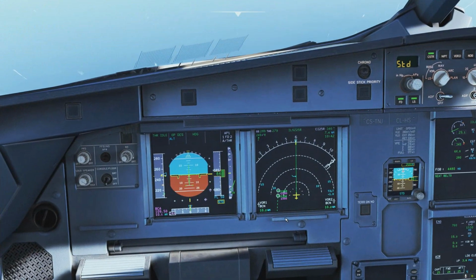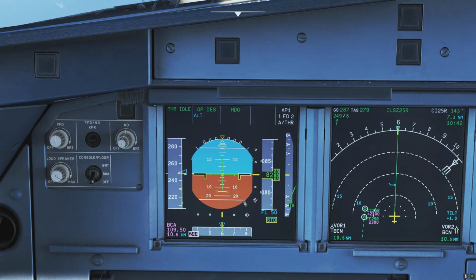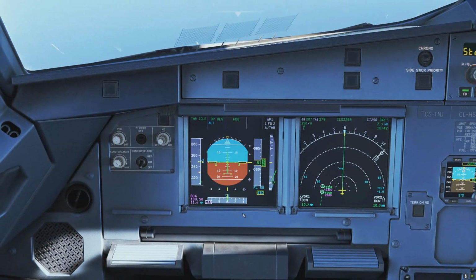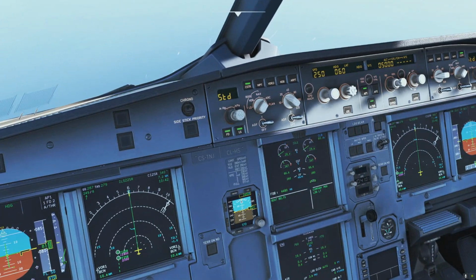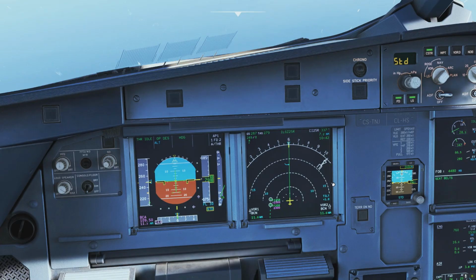Okay, as we are now on the approach side of the ILS, another indicator for us is of course the ILS itself. So we can see here very clearly that we are too high. ATC now tells us descend 3,000 feet. So that tells us that very shortly they are going to turn us in for the ILS. We're still high. We cannot fly any faster. We are still in open descent.